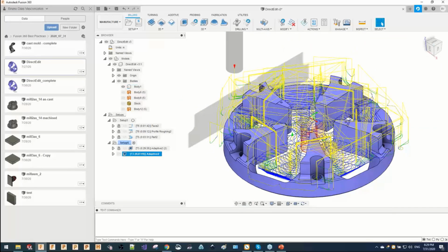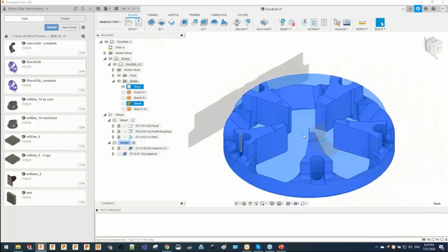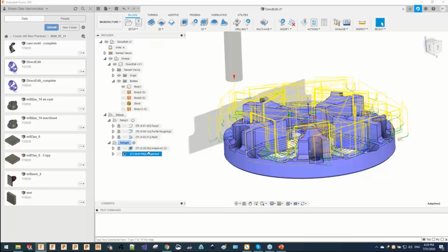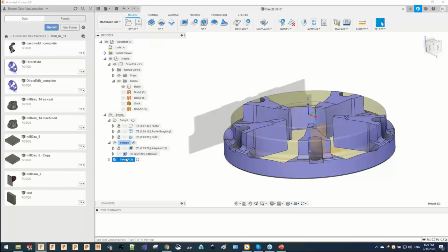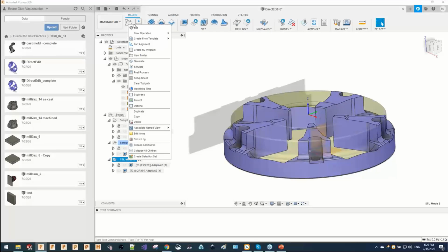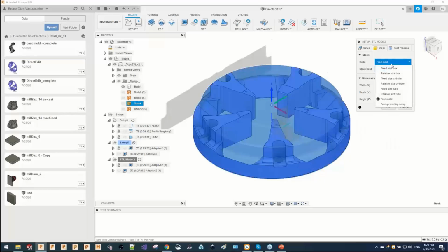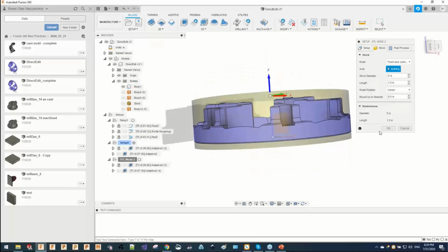I'm going to show another example that I think is pretty good. But in short, this is one of the ways you can use STL files. The other way that you can calculate rest material from STL, in case you don't have any, let me create another setup over here, and this is STL mode 2. Try 2. Let me just do this and click OK.